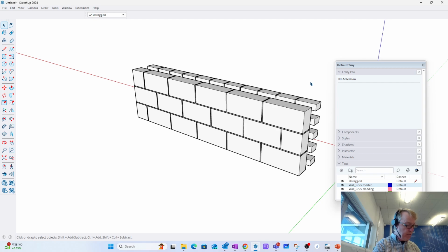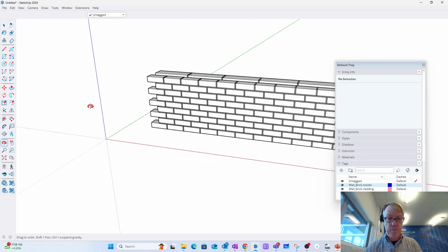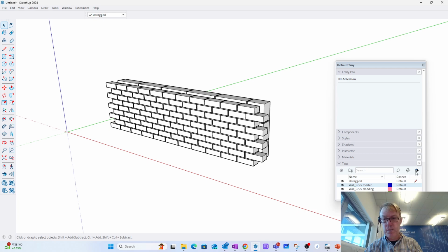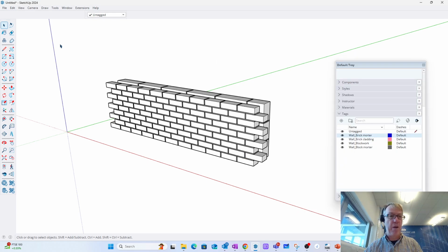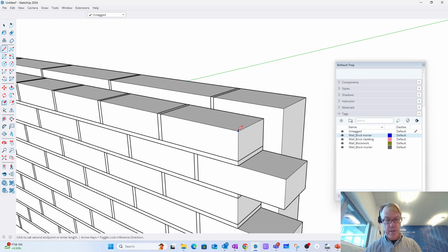The next thing we want to do is to create some other wall elements. Perfect. So the first thing we're going to do is a cavity closer. It'll be a 20mm deep cavity closer. So I'll just draw a line in this corner on the up arrow, 20mm, enter. And for my sanity, no, it's fine. I'll use the rectangle tool. I'll go diagonal to diagonal.